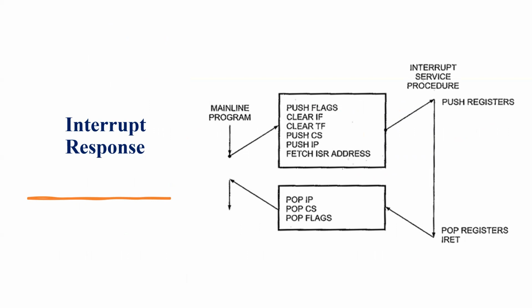See here, friends, what our 8086 can do. This is the program execution our processor was doing right now. At this junction, it receives an interrupt and it is willing to provide a service for it. Before shifting our execution to the interrupt service routine, it has to do a few things. Why? In order to avoid problems after completion of the service routine, once we come back to our previously stopped program, we should not face any problem. That is only possible if we do all these things before shifting our execution from here to here.